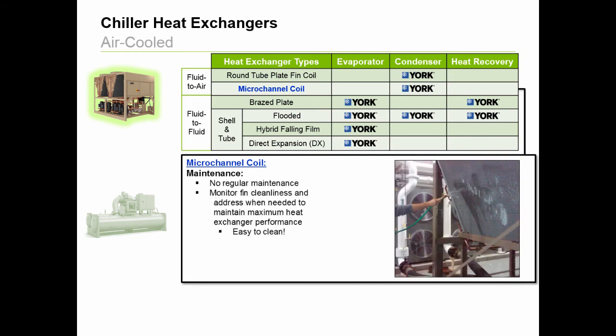However, like any fluid-to-air coil, there's the potential for external fouling due to leaves, dirt, or dust. In this case, cleaning is very easy, with low-pressure, potable water, and if needed, a soft bristle non-metallic brush. Two upkeep advantages with microchannel coils are they are always a single row, meaning it's easier to spray water through them to flush out debris, and due to their design, there is minimal risk of bending fins, as microchannel fins do not extend past the tubes. Both of these mean the owner will spend less time and money cleaning coils, and more time enjoying smaller utility bills due to high efficiency operation.